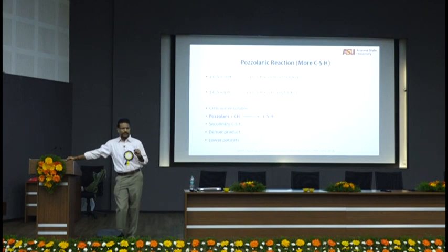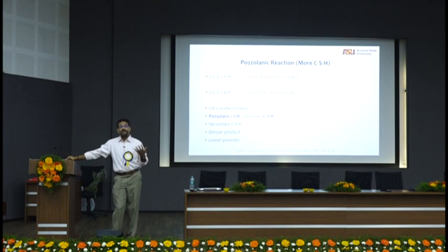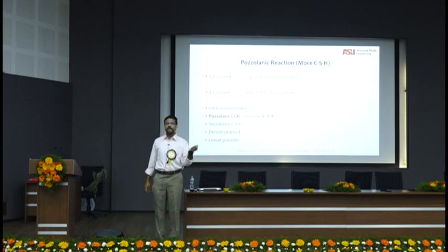The concern should be, is my fly ash too coarse to be put in the system? Is the carbon content of fly ash too high, causing problems like rising of carbon to the surface, interacting with other chemical admixtures? Is my fly ash having too much residual carbon? Is my fly ash high in alkalis? Those are the questions to ask rather than blanket saying, I will allow only 30% fly ash.